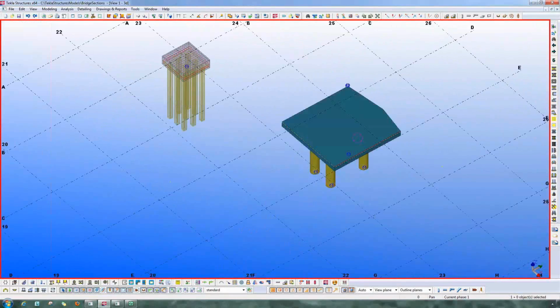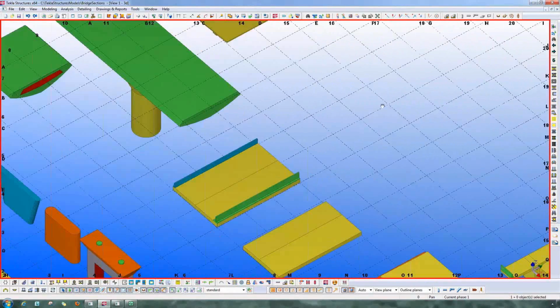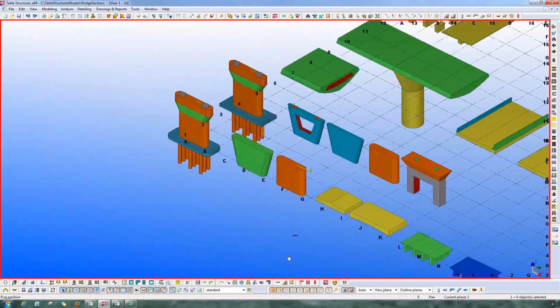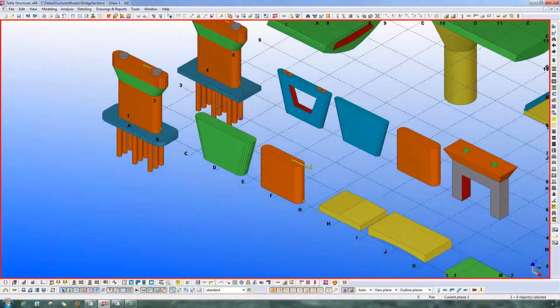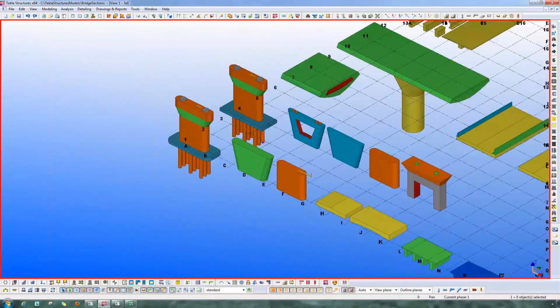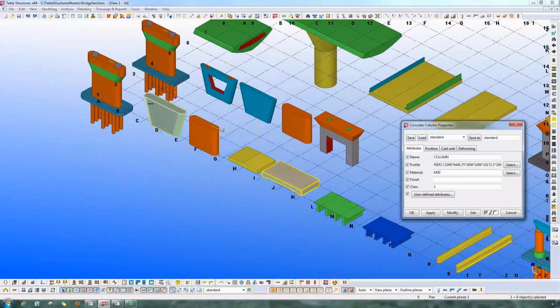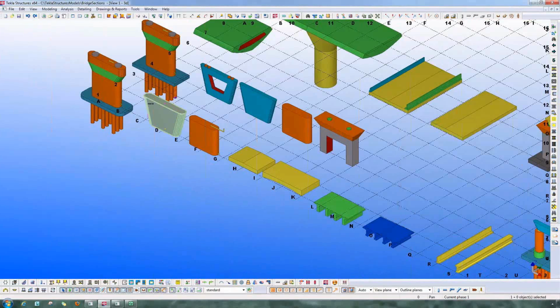And coming to one more area, that is for the piers. So here we have the different types of pier arrangements where we can model very quickly the simple, the semicircular one or the square one, or with the openings or the tapered portion. I'll demonstrate those areas here. So if I select this, there is a profile defined. So I'm going to model one column now.